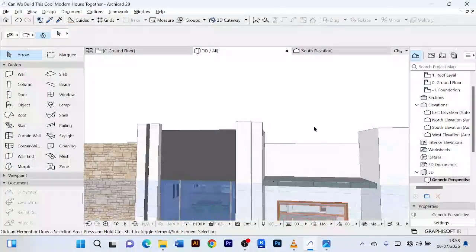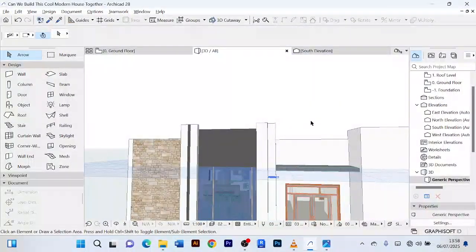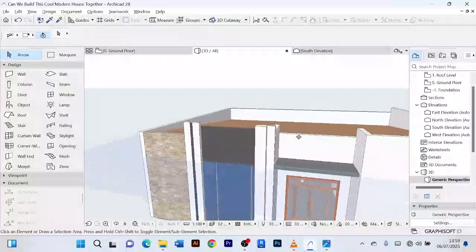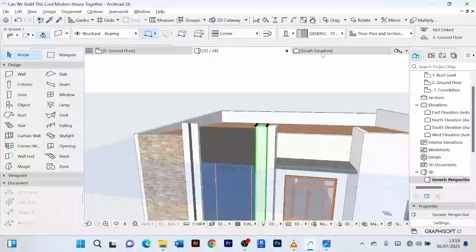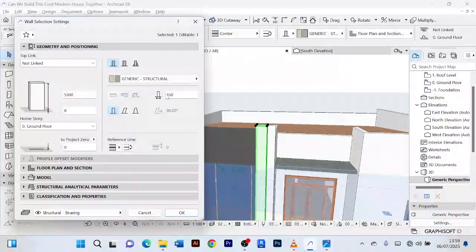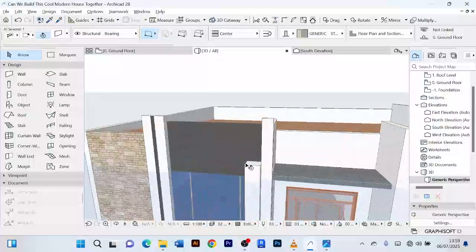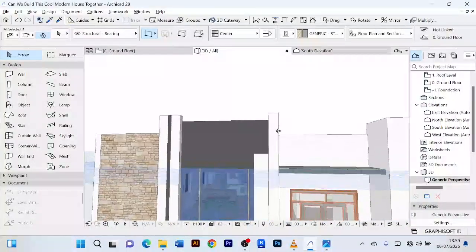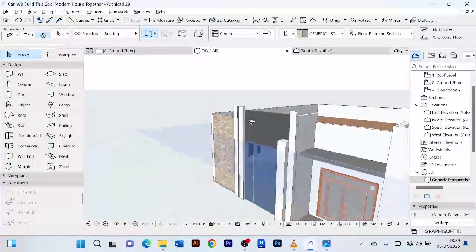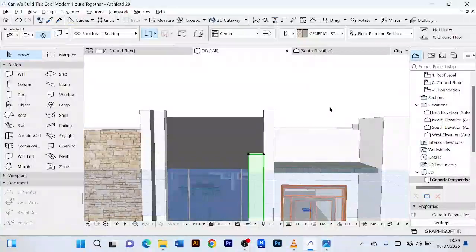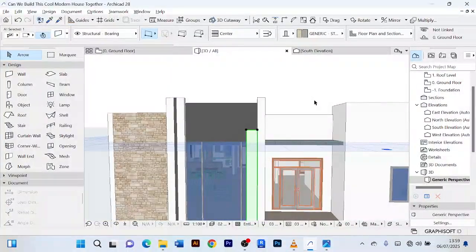Then you come to the 3D, you'll have something like that. However, it is not going to be as tall as this other one. So I'll control that by Control T. You come to the height here. So you reduce this height to, let's first try 4 meters and see what we have. Well, that is exactly what I wanted. It is a perfect height for me. That's where I want it to be.